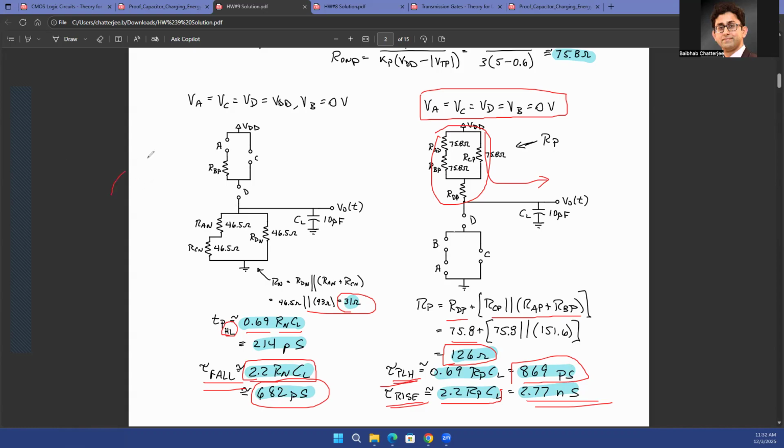For example, if my rise time is a particular amount, let's say T rise, my signal does not even rise to VDD if I have not spent that T rise amount of time. And then you need to have a T fall, which is again some amount of time. So the minimum time period for that signal is going to be T rise plus T fall.